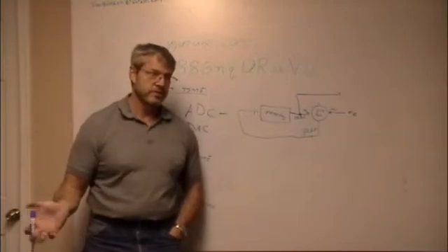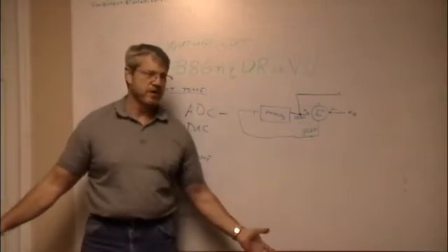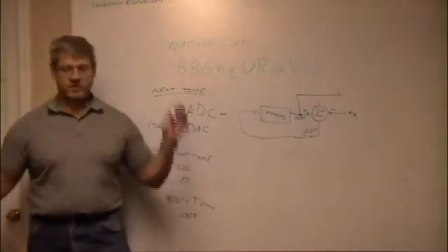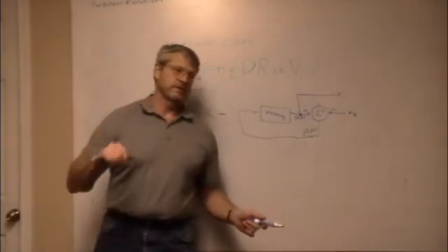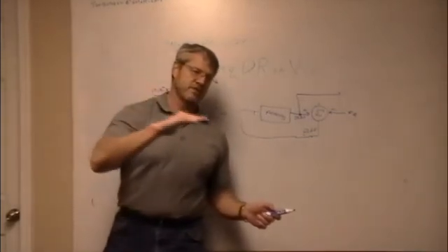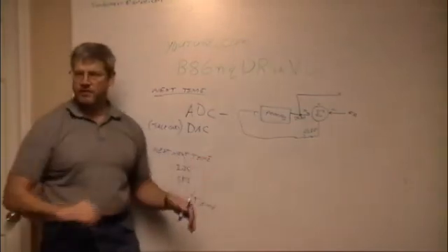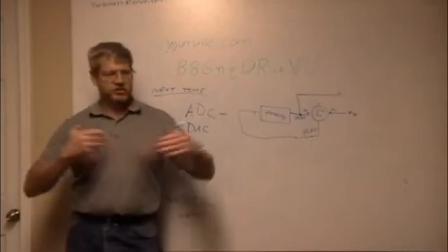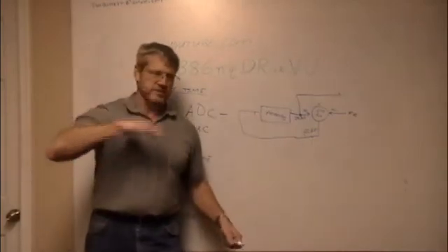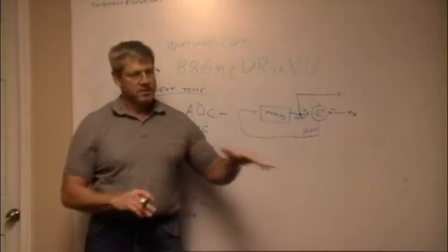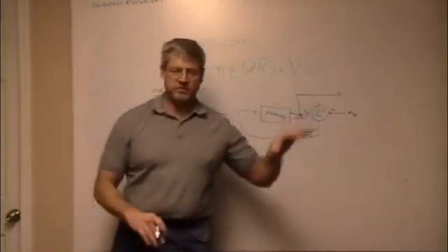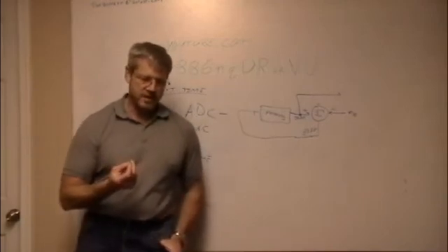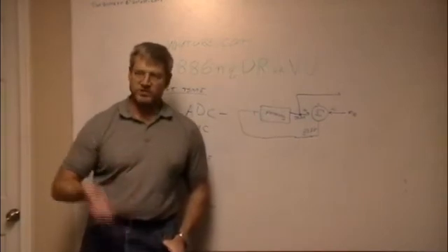Now you can add an integral term, which is effectively an average over time, and that smooths things. It says, oh my God, I've turned on, but now I've already been on and things are going down, and I see that they're going down, and I don't want to do anything for a while. I'm going to let it go down. That stretches those things out over time and gets rid of this chatter, that's what they call it. But now you get maybe bigger dips. So then you add a differential, and the differential wants to bang bang.